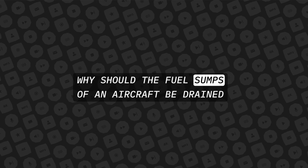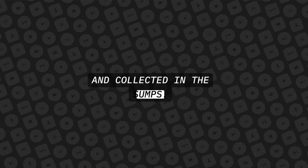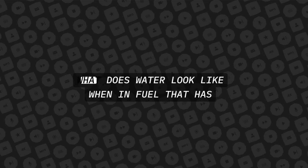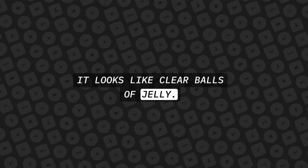Why should the fuel sumps of an aircraft be drained before the first flight of the day? To remove any water that has condensed in the fuel and collected in the sumps. What does water look like when in fuel that has been drained from the sumps? It looks like clear balls of jelly.